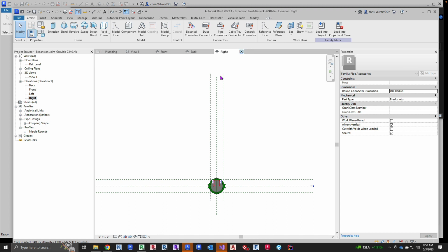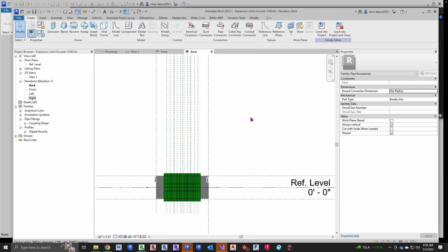One other question I had was, I know you said that you build almost all of your families in Revit. When would it be advantageous to not use Revit? Never. No, I get that. Obviously, let's use Revit, but are there cases where I could easily build a Revit family in Inventor or whatever? Inventor would be another good place to build a family because you can make them flex.